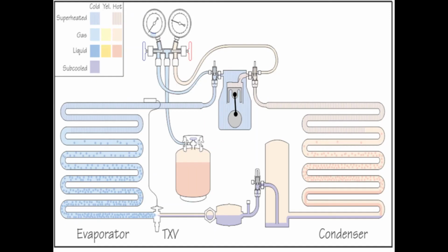For vapor charging, the connection of the manifold is done on the compressor. There is no problem of connecting the manifold on the compressor because we are dealing with vapor charging, and we know that the compressor has no adverse effect with vapor instead of liquid refrigerant.